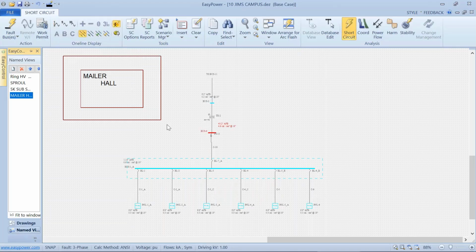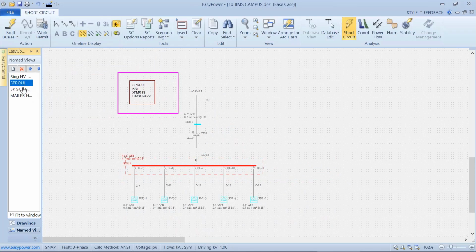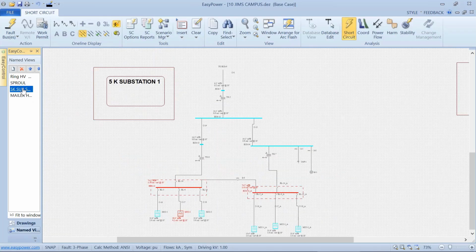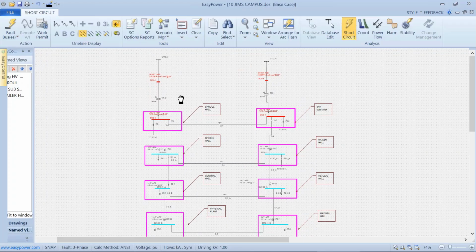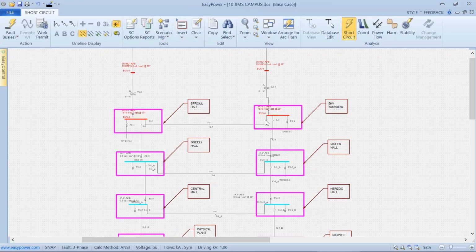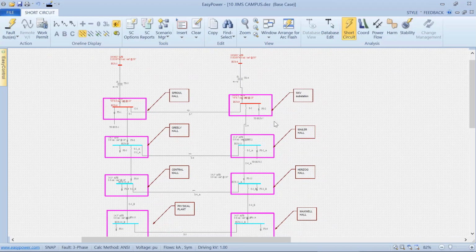Likewise, if I want to do arc flash, I can calculate that and feel fairly confident that the whole system is being analyzed at the same time. Now, one side note, because these go through some pretty hefty transformers, in isolation, it is possible with the process of equivalization to make an equivalent circuit upstream from my transformer.